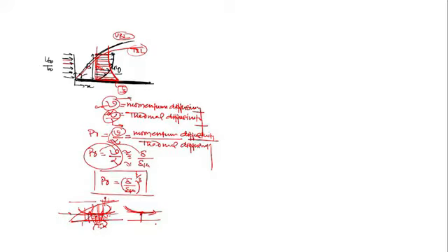So I told you, as the boundary layer grows, as the flow progresses in the x direction, the heat that is conducted into this layer is swept downstream, and finally it is transferred to the fluid outside the boundary layer. Because as the boundary layer grows, this will transfer to the outside of the boundary layer. As you know, we have already solved one question, there is also some mass transfer in this direction. Whatever mass has been transferred through this layer, m1 is equal to m2 plus m3. Yes or no? I have already shown you that in the previous lectures.